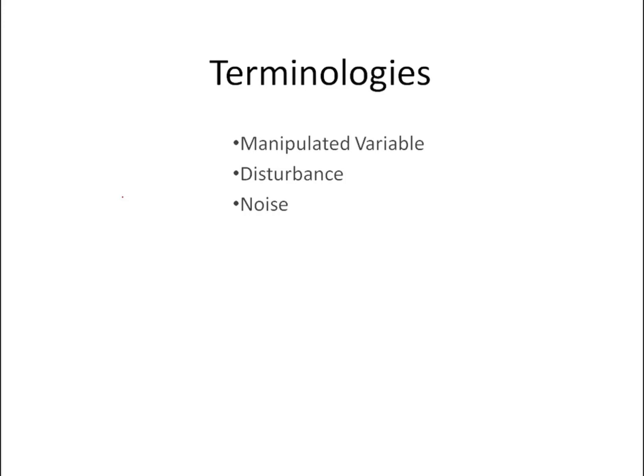Noise is another kind of input to the system. Mostly it enters the system whenever we are trying to measure a certain variable of the system. It is a high frequency phenomenon. The servo mechanism is a kind of control system where the control variable is either displacement, or the time derivative of displacement, or the double derivative of displacement. So this is the displacement, velocity and the acceleration.